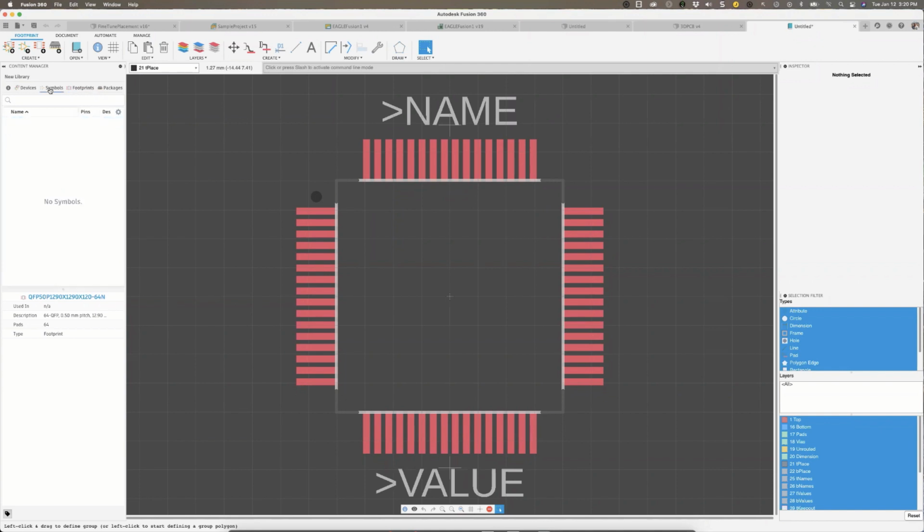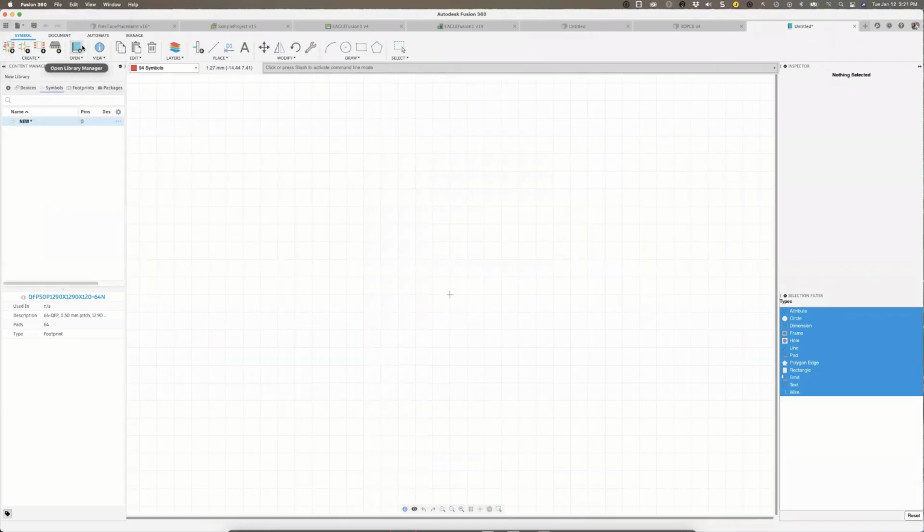The only other thing, I always like to give a little tip: remember that in the Fusion library symbol editor, when you're creating schematic symbols, under place we have something called pin array. So if you're creating schematic symbols and you're okay using standard names, you could click here where it says pin array.